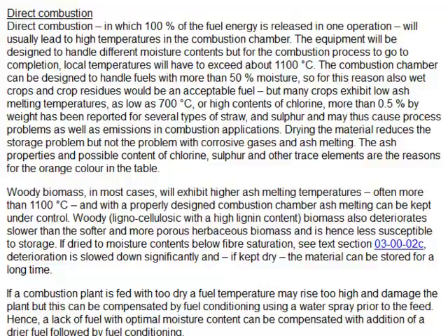But the main constraint is, of course, that the fuel must be combustible, so that the fuel itself shall be autocombustible. It shall be possible for the fuel to burn without any extra energy. This constraint obviously effectively excludes all types of sludges where the water content may well exceed 80 or 90%. So they will not be combustible and it will not be an alternative to put a wet sludge into a combustion chamber unless you have a base fuel so that the combustion is already running.